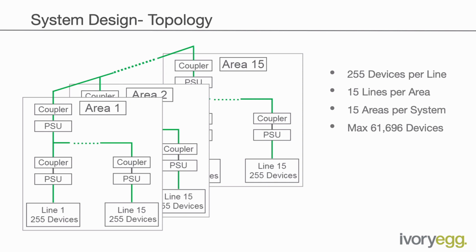Now that leads people to say, well, with the system being so large, surely there's a lot of overhead when you're designing small systems, maybe a small residential installation, working with such a large system, adding complication and cost. Well, it's just not true with KNX because of that decentralization. Because you just need a power supply and the devices you need, there's no central servers, every little device has its own intelligence. There's no additional cost.